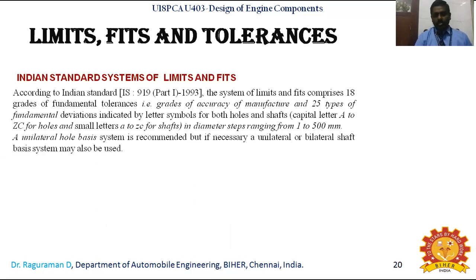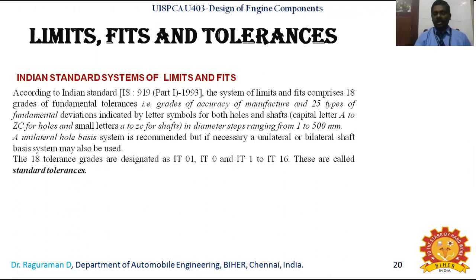The unilateral hole basis system is recommended, but if necessary, you can consider bilateral. Unilateral or bilateral basis systems may also be used. The 18 tolerance grades are designated as IT01, IT0, and IT1 to IT16. These are called standard tolerances.